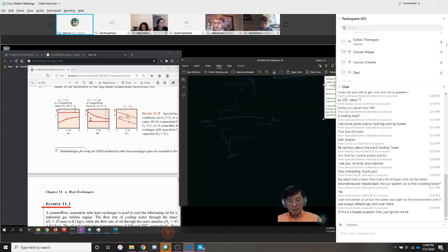And so what happens here is that you might then have a big exit, right? And this might be methanol vapor, CH3OH vapor, right? So you might have a vaporizer, right? So in this situation here, you have liquid methanol that's going in, and you want to vaporize it, right? And you would pass, let's say, hot water. You put in hot water, maybe 90 Celsius, not 80 Celsius, and you get it out. And what happens is that the methanol vaporizes.